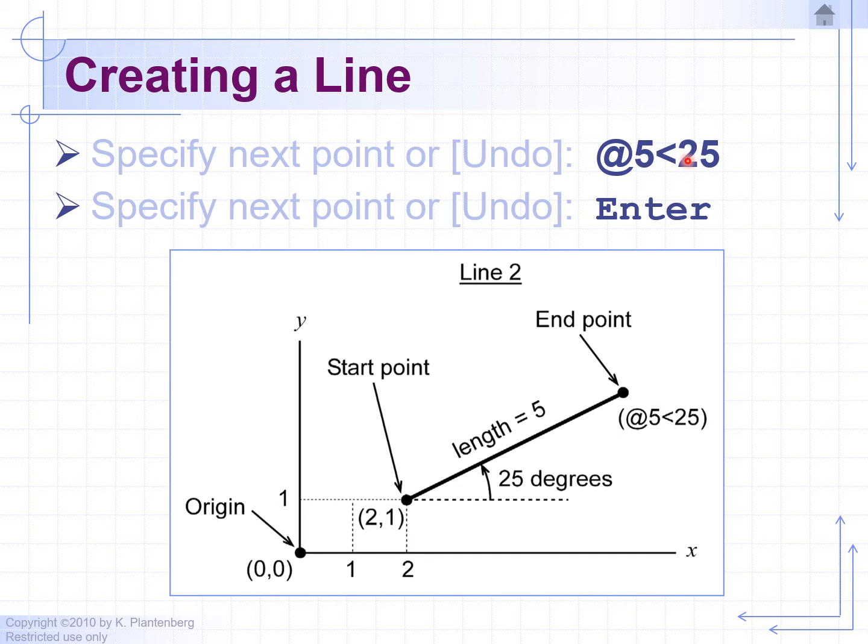And the angle, we'll lock it in, so we're going to type in shift, comma, to access the less than symbol, 25 degrees, with respect to the horizontal, 25 degrees counterclockwise, and that'll locate our second endpoint, hit enter, and it will generate the line. Next slide.